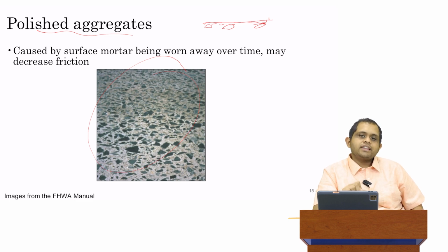So you certainly don't want this type of situation to occur on highways where you're driving at high speeds and you have relatively large and heavy vehicles. But on many urban rigid pavements in India, you'll see something like this. It's not something that cannot be tolerated. And that's why they're generally there and they don't require too much work. Again, the key is the type of aggregate. Generally, we always avoid polished aggregates or very smooth aggregates in road construction, exactly for this reason.